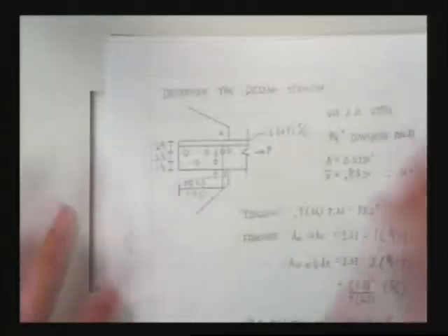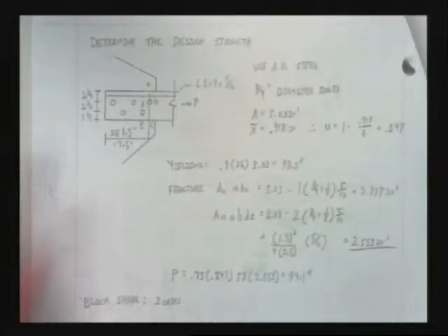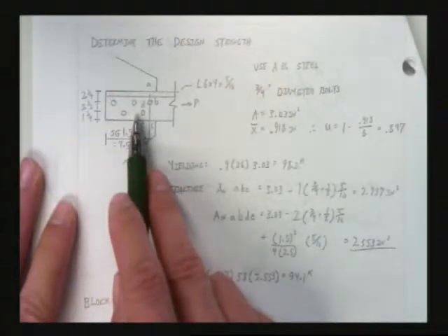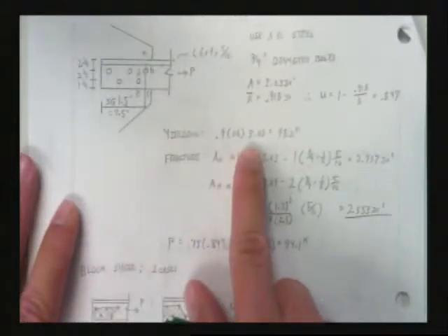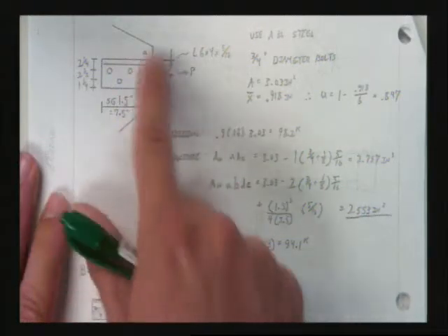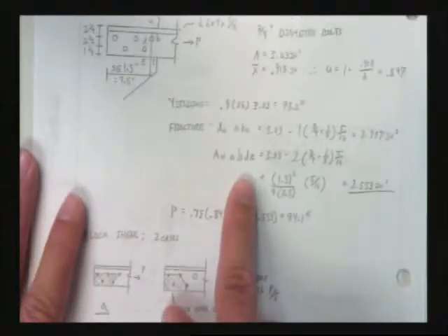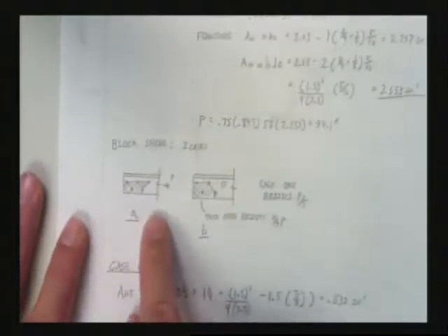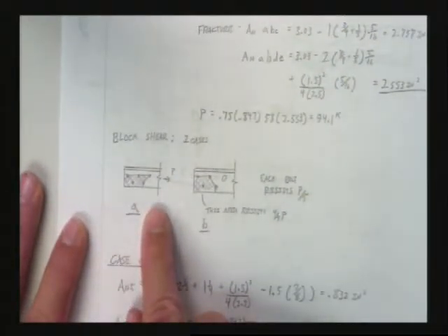So, a problem like this. Got an angle. Got bolts, diagonals. What are we going to check? Yielding, fracture. Notice I checked 2 paths. Straight across and then at an angle. Hey, we know how to do that, right? S squared over 4G, right? Yeah. Great. Block shear. Oh, Nelly. Diagonals and block shear? Sure, if you can dream it, then it can happen.